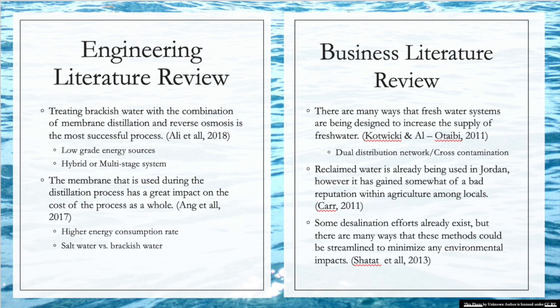This study found that layers of the dissolved salts are collected on the membrane and inhibited the ability to purify the water. The cost of the membrane was not shown to be worth it to save on, since it could compromise the results and negatively impact desalination efforts. Combining multiple purification processes is the only way to ensure that the brackish water would be pure enough to be used in potable situations such as drinking.